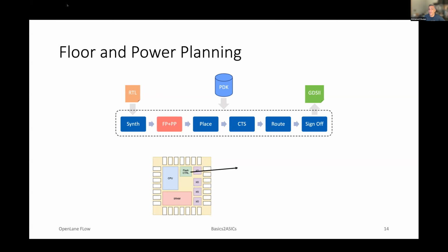But the floor planning of a macro will be different, because the floor plan for a macro defines the area of silicon that will host the components of the circuit that implements the functionality of this macro. And typically these components will be placed on virtual rows, because these components are regular in shape, typically rectangles with fixed height. So they are placed on these virtual rows, and part of the floor planning also is to specify where the inputs and outputs, or the pins, are.